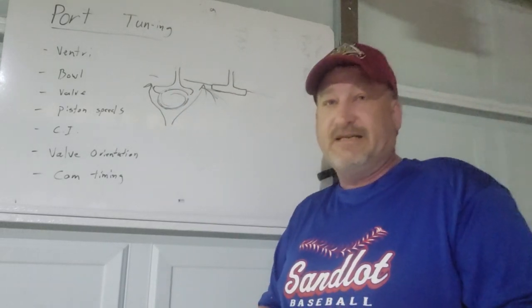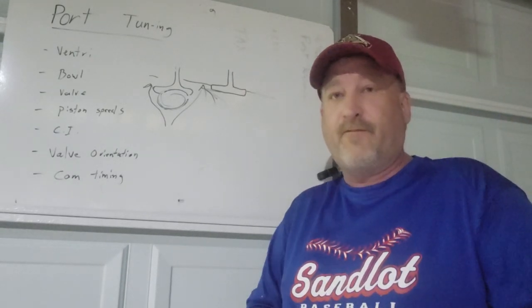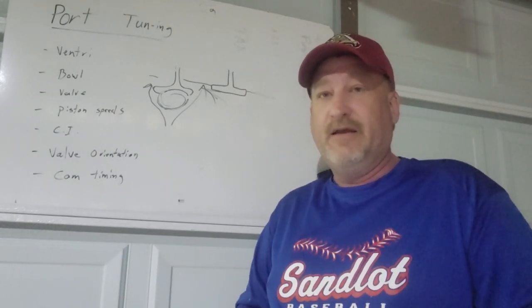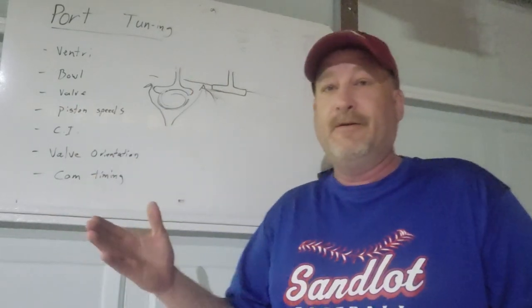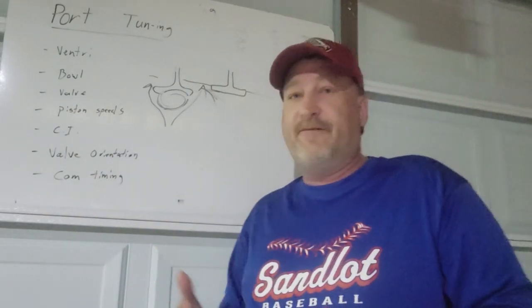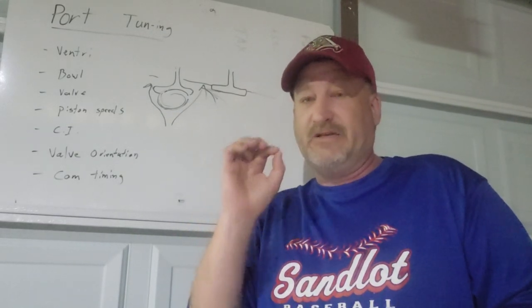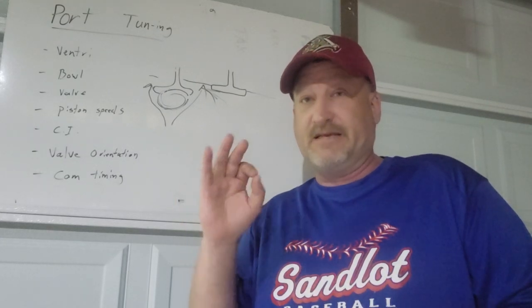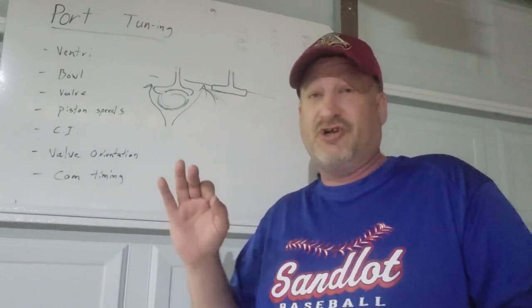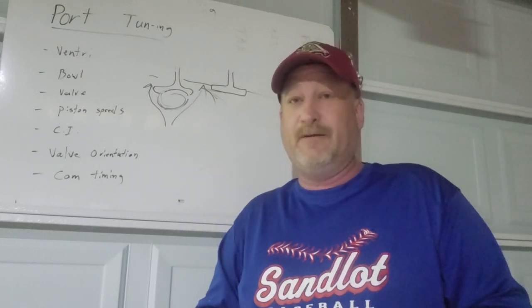So by increasing the exhaust valve size, is there necessarily any performance gained from doing that? Again, it's related to the port tuning. The majority of your exhaust gases exit the moment the exhaust valve leaves the seat. More than 70% of the exhaust event actually occurs within the first 250 thousandths of the valve lift.